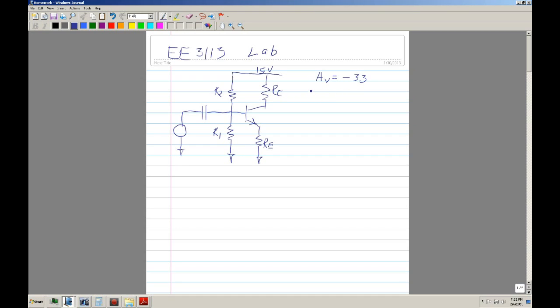Okay. And then he's got an I collector, and then Q. Q means quiescent current, meaning that if you don't put any signal, it's the steady state. In other words, remember when you do the SPICE simulation, we do an OP, and it gives you the voltages on the SPICE. Okay, that's quiescent. In other words, you don't have any signal voltages, so that's OP, operating point. It's quiescent. In other words, that's the current that the transistor's driving.